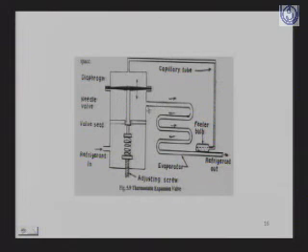The next one is the thermostatic expansion valve. This is a type of thermostatic expansion valve. What happens? This is a valve. This is the valve seat. This is a diaphragm, and this is a capillary tube. This is the evaporator. The refrigerant comes from this place to the evaporator, and this is the refrigerant out.